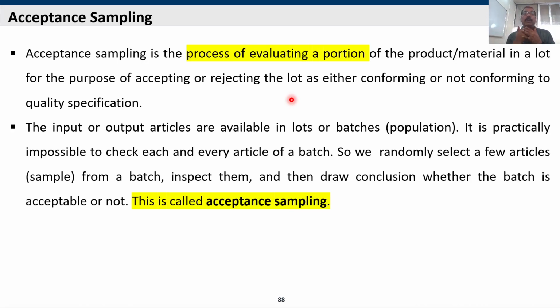In order to confirm whether the selected samples are under control or out of control, if out of control we can consider whether to reject the whole lot or do a recheck or rework. The process to check the sample for acceptance is called acceptance sampling.